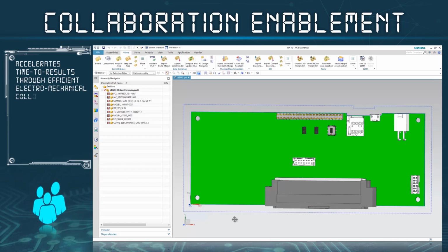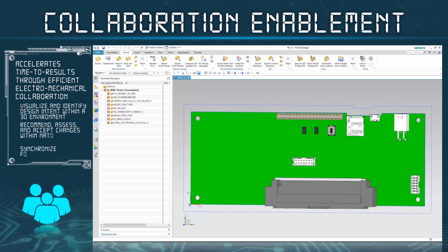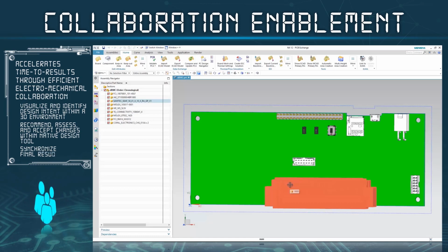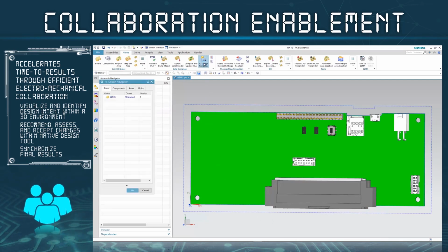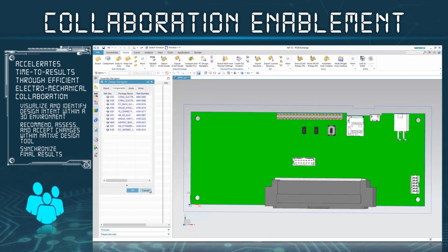Typical PCB outline and mechanical interfacing components are defined by the mechanical engineer. During our demo, we'll be using NX from Siemens and Expedition, following a design flow used by best-in-class companies. Here you can see the mechanical engineer has created the board outline and placed critical components. Opening the PCB Navigator, we can see all the objects that can be passed to layout: components with refdes, part number, mounting holes, board outline, special shapes.